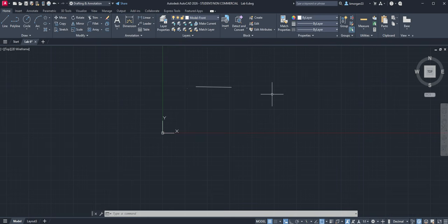Of course, away from each other, you have two points in a line. So your line is made of 2 points, the initial point, and of course a series of points on the line, and the end point is here and the start point is there. The distance from the first point to the last point is 4 units, so 4 inches that we just made. That is called the direct entry, which is your direct distance entry.